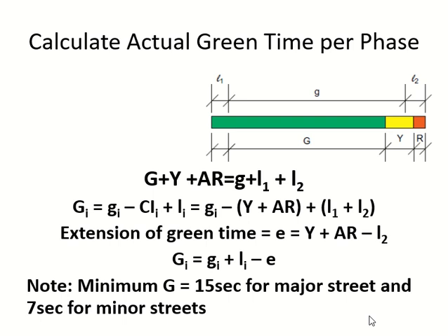Effective green comes from the cycle length. Last time we already discussed, we have standard values for that, and we can measure it as well. Using them, I can calculate the phase. From the phase, these two have an equation, so I can then calculate the green. This is the actual green when the signal will show green light. That's why we need to know. Effective green is just for us.